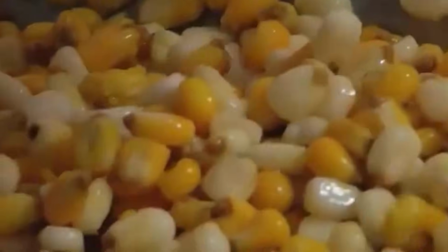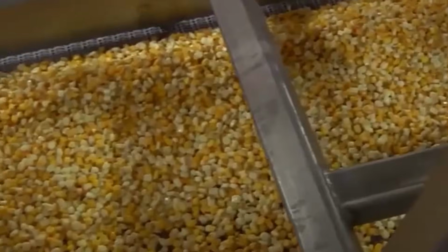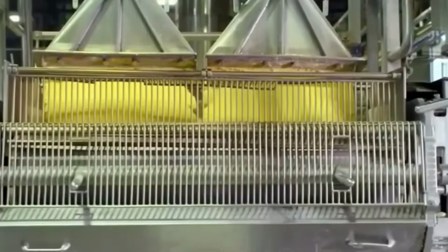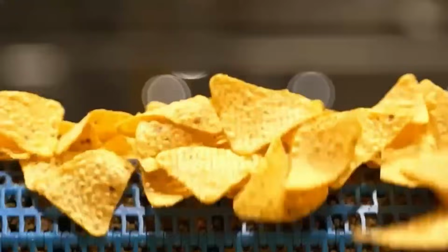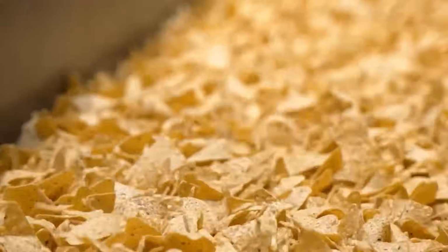Cut chips move on a perforated conveyor where they are lightly dusted with corn flour to prevent sticking, and then enter a 3-zone oven. The oven zones are independently controlled for temperature and airflow. The chips are partially baked at 300 to 400 degrees over a total residence time of 45 to 60 seconds. This reduces surface moisture and creates a semi-rigid structure suitable for frying. The internal moisture content is reduced to around 20% by weight. Partially baked chips exit the oven and are transferred via vibratory conveyors to the continuous fryer.